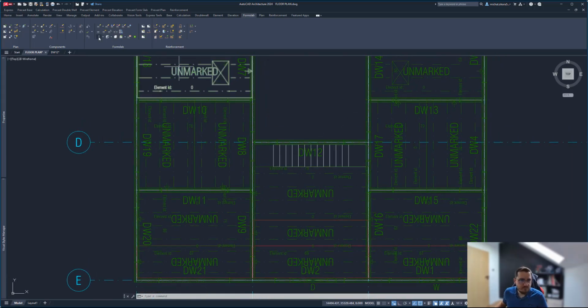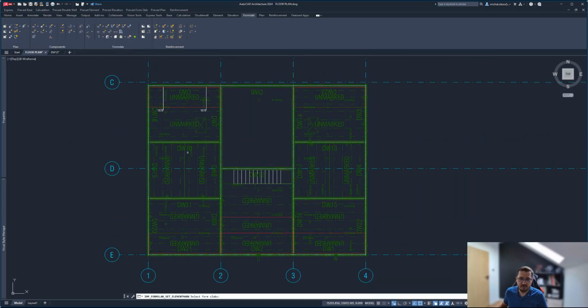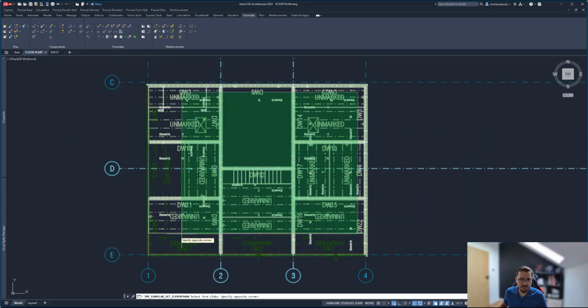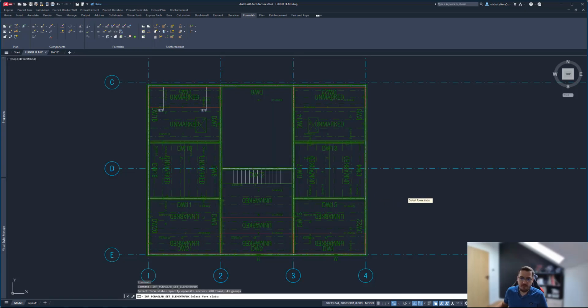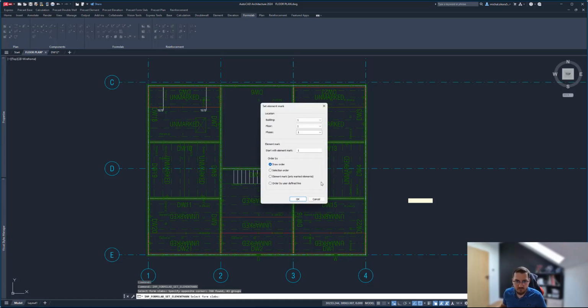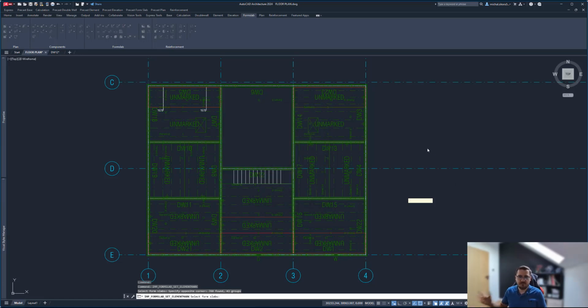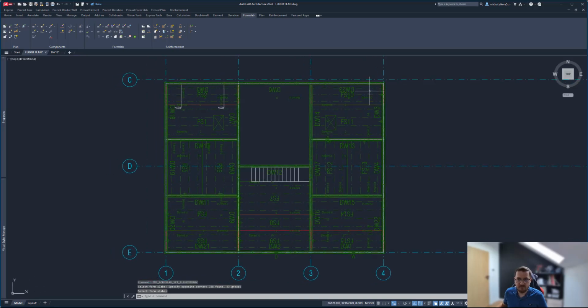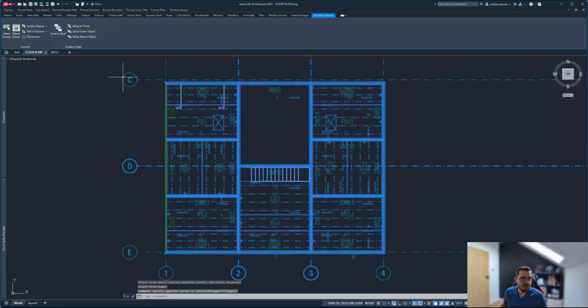With that, let me go ahead and actually in this instance actually let's set element marks as well, because you need to set those element marks for form slabs. So I'll just select that. It will find which form slabs are identical, which are not, and yeah, that's it for draw order. So those elements, those slabs are now done, and now I can save those slabs.